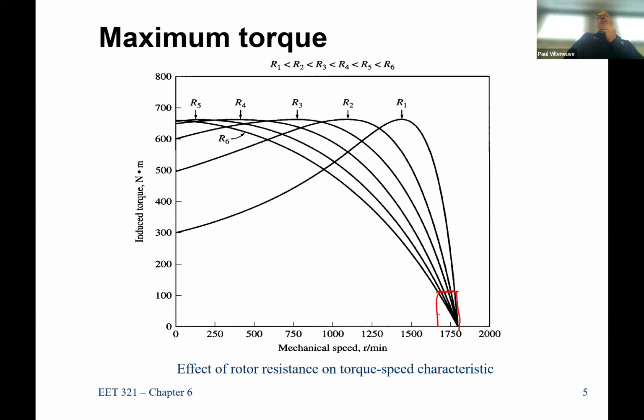So running it at a design B by default means you're a more efficient machine because you're running closer to synchronous speed than any of these other designs. So in addition to R2 using up energy, also just the operation of the motor itself, you get higher rotor copper losses just in the built-in resistor or the equivalent resistor for the rotor circuit without running anything different. So more efficient means running it at this one as much as possible.